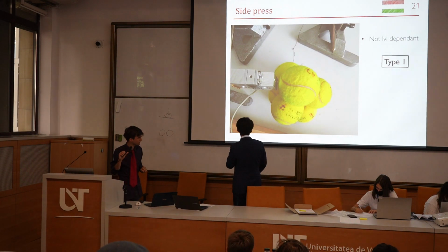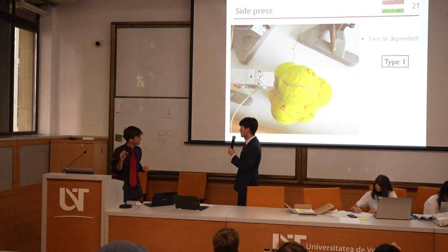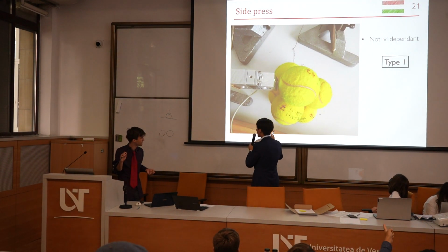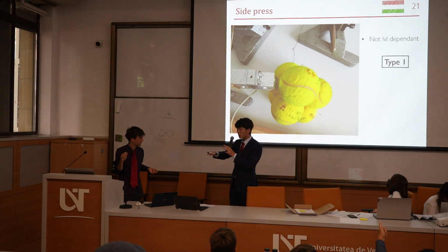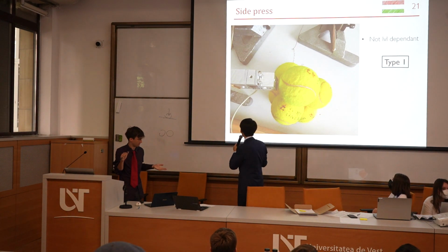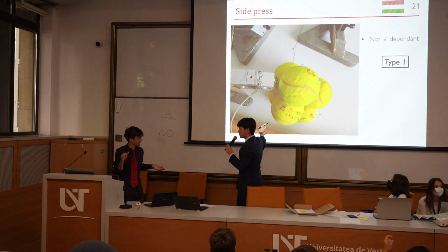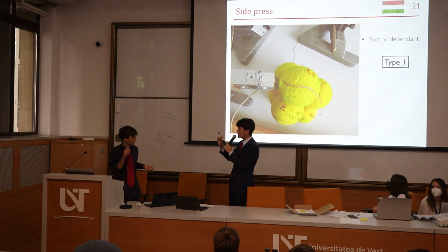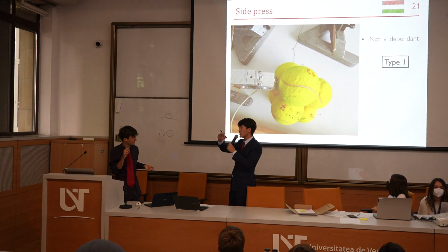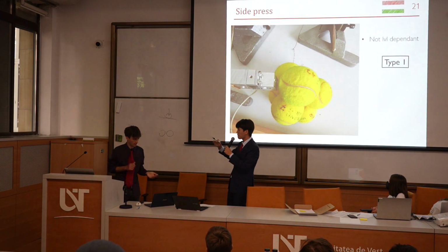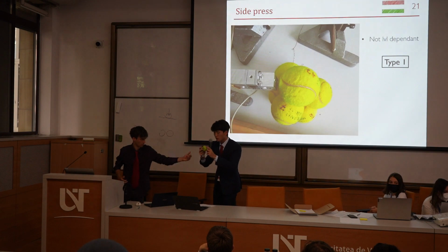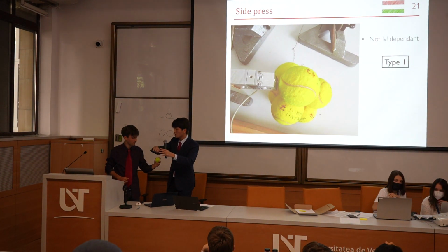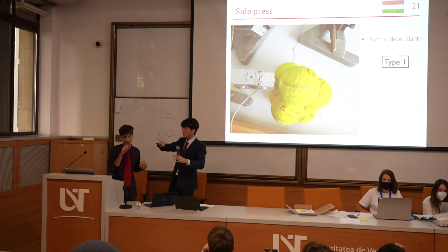So we think that the variance is a key factor, and you can use error propagation, which means that you can imagine that the tower sits on the plane and goes on top, right? So if you have a variance in one layer, a slight variance in radius and mass, you will cause an uneven surface, right? So if one ball is this and the other is a little bit bigger, you will cause the surface to tilt. Okay, yeah, I understand.